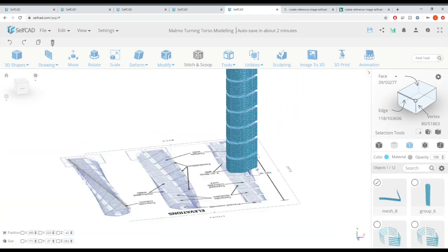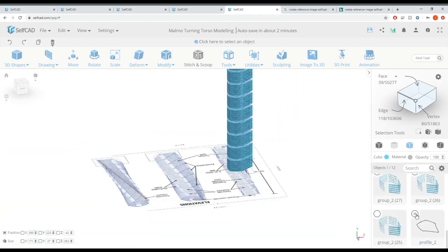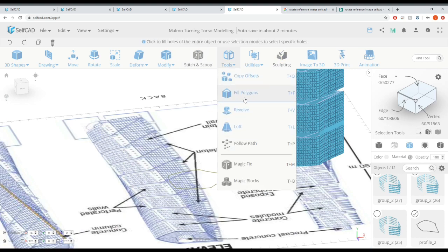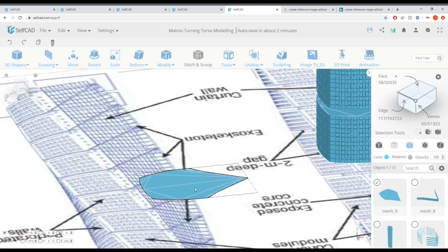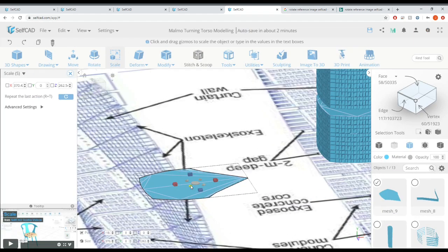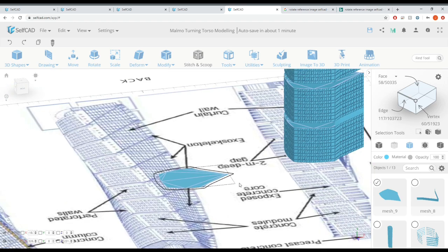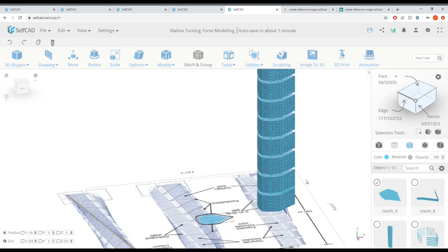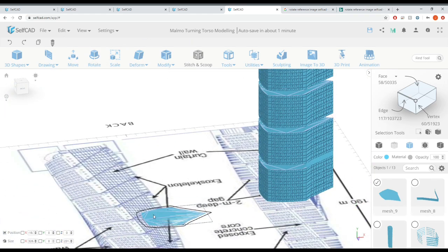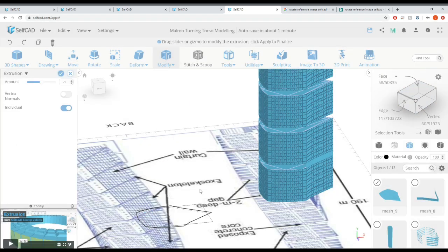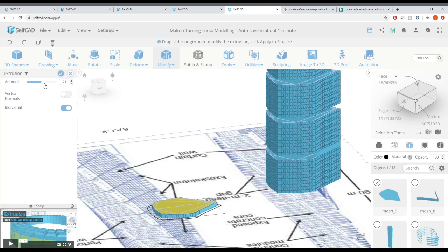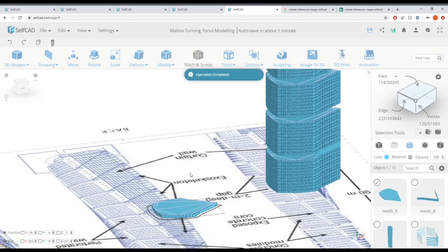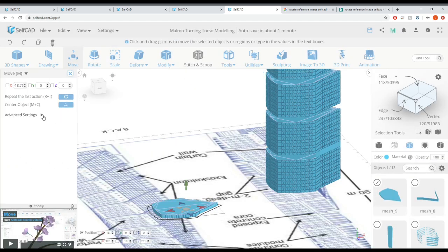And the next stage is to create some walls on the inside so it doesn't feel like these separate sections are floating. And for that, I'm going to reuse that outline of the plan that I made hidden a while ago. I told you it's going to come in useful again. And I'm just going to rescale it on the center to become a little bit smaller. And I filled the polygon, and now I'm going to be extruding it. See, if you go -1, you don't see anything. So make sure you have a positive value on that. Push it up.